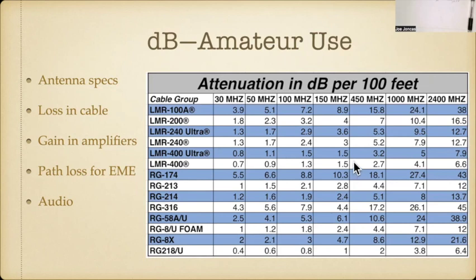I think they're 50-foot sections. I've got some rolled up under the deck. I'm just asking to understand the dynamics here. If it's a shorter piece, you have less loss. That's why in your shack, I like to use RG8X, this here, for short cables. Because if it's only 3 feet long, it's going to have very little loss and it has no trouble handling 100 watts. And it's easy to work with.